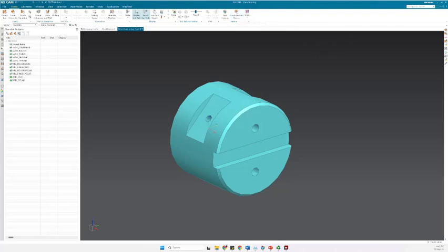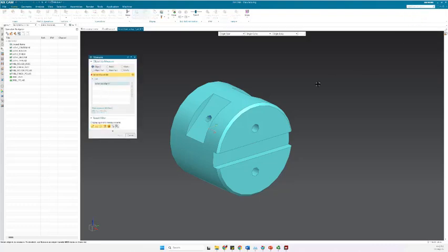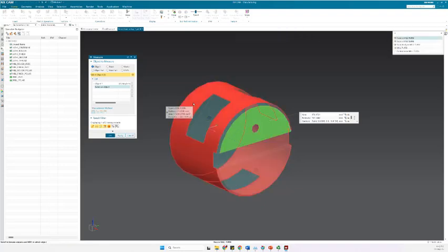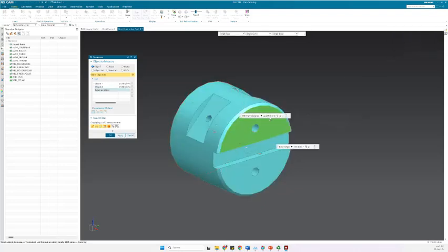All right, so the first step, if you remember, was to measure the different diameter and then the length. So for the length of the part, I just type measure. I'll search, I'll put this point, and then if I wait here, now this three dot will appear, and I'm able to find the face behind that. So I can see that the component that I'm going to work with has 32 millimeter length.